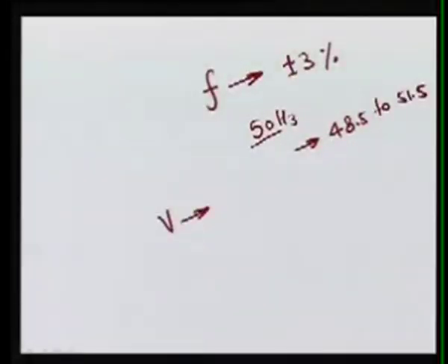Similarly, in terms of voltage, for the EHV system, that is extra high voltage, more than 220 kV, we have to go for only plus or minus 5%. It can be plus or minus 10% for the lower distribution system, meaning the HV system and the medium voltage system. These are the standards, because if you operate beyond them, there are many possibilities that your system will not be stable and reliable.